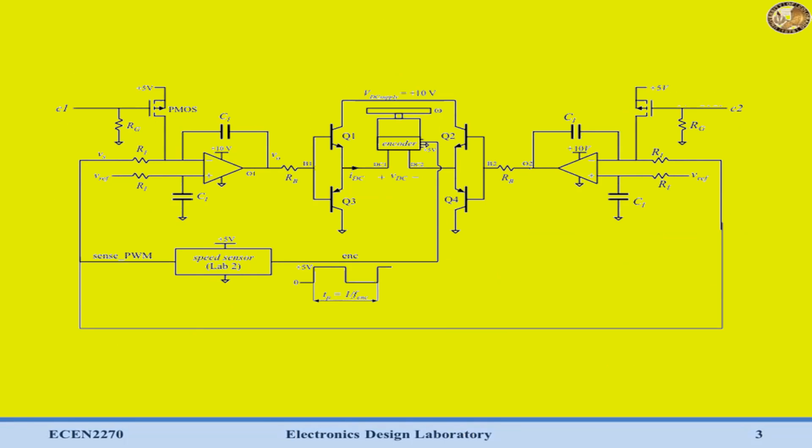If you recall, our full circuit is going to look something like this, where we have our motor driver in the middle, and then a speed controller for both sides of our motor, or a feedback controller for both sides. We're going to use control inputs C1 and C2 in order to change directions on our motor, where only one of these will be high at a time, which will enable a single one of our control loops. We have a single speed sensor circuit, and we can use the output from that speed sensor circuit for both of these feedback circuits.